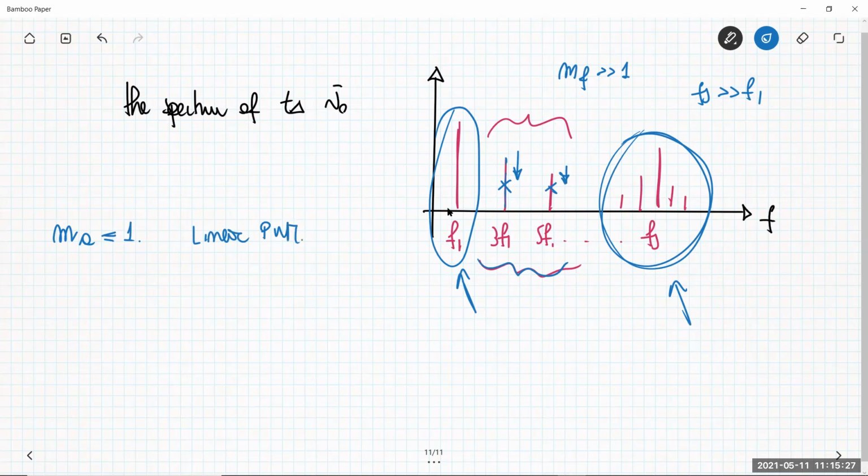In that case, I'm using the comparison between the sine wave and the triangular carrier wave inside the modulator to translate the information of the control voltage, basically the frequency and the amplitude of this control voltage, into a variation of a pulse width.